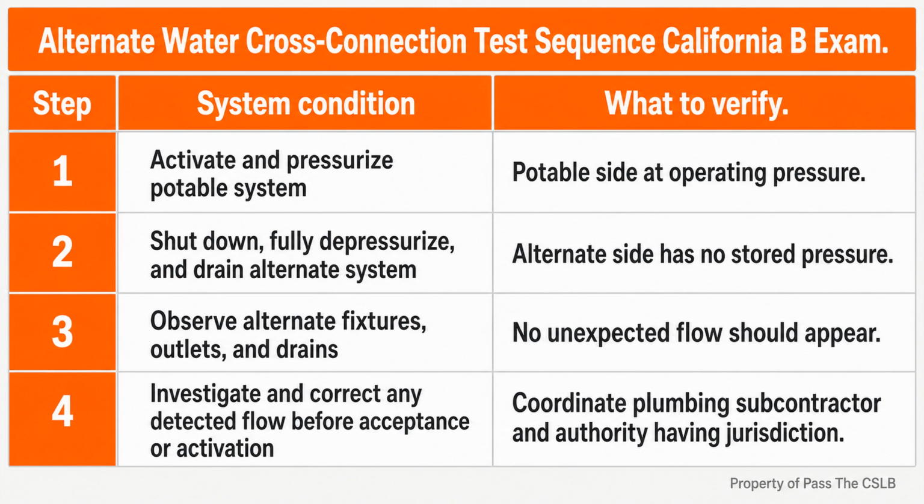Imagine a hypothetical summer framing site. One hydration station uses a tightly closed, insulated dispenser with a tap. Another station uses an open container where workers dip cups. The second arrangement creates a sanitation problem, even if the water started clean. Now imagine a process hose lying below the surface of dirty water. A sudden supply pressure loss can turn that hose into a backsiphonage path. The permanent building and the temporary site are governed by the same basic discipline. Protect potable water from contact and reverse flow.